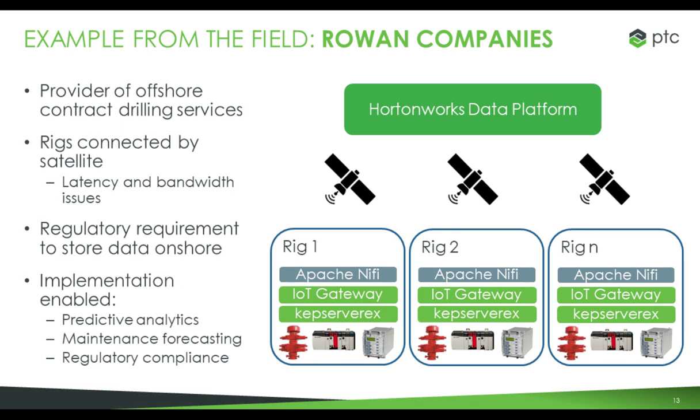So in terms of the data that they needed to gather according to these regulatory requirements, they were pulling data from the blowout preventer, the managed drilling systems, as well as some of the electrical systems on the rigs. And so they chose Kepware to use a single application on each rig to aggregate all those data sources, or just connect to all those disparate systems. And then they used Kepware's IoT gateway to convert all of that data into the MQTT protocol and send it to Apache NiFi. So this is sort of where Apache NiFi comes in.